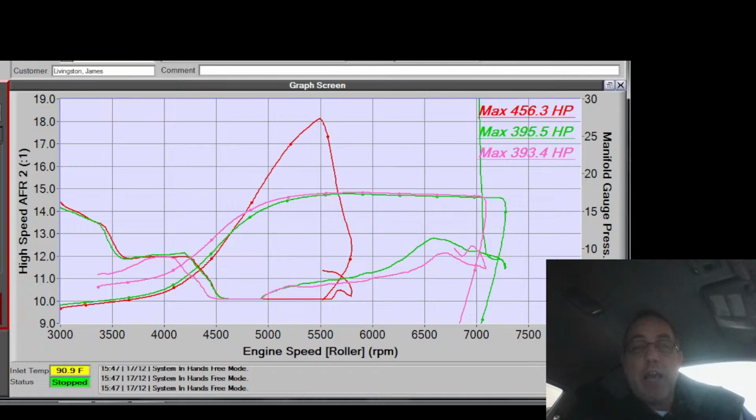And really, I should clarify, it doesn't use either of those. Well, not either. That's a lie again. Let me clarify even more. So, tip-in is largely throttle-based, but there's also map delta-based tip-in. Factory ECU uses both. Link can use both if you enable the wall wetting functions and all of that, and a modeled fuel model and not just a regular traditional fuel model. M-Tron doesn't really do tip-in like everybody else does. It doesn't do anything delta map at all for tip-in. It's all throttle.